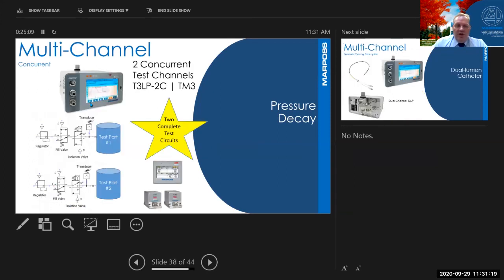What we really consider true multi-channel is we have a pressure regulator, our 2 valves, the pressure transducer and a test part, and a completely independent circuit for test part 2. We can do this on our Tecna T3L series with a 2-channel there, or we can do it with the TM3 series, but it's really 2 complete test circuits. So a lot of times routing valves and things like that get confused with being a multi-channel. Multi-channel to us is really independent testing.